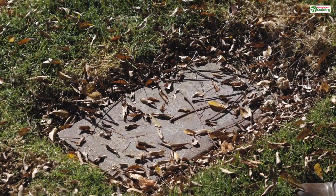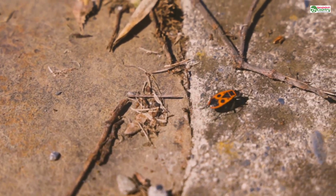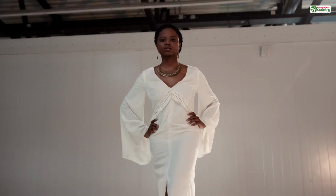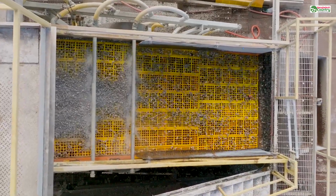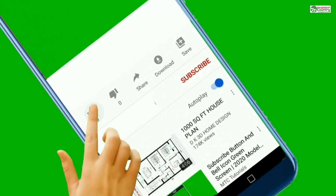So, how do you find and exterminate these 4 horsemen? Your first line of defense is often a single magical button. Most 3D modeling and repair software like the free programs Meshmixer or Blender have an automated repair tool. It might be called Make Solid, Auto Repair, or Watertight. When you click this button, the software analyzes your entire model. It aggressively hunts for holes and tries to patch them. It looks for those rogue internal faces and deletes them.